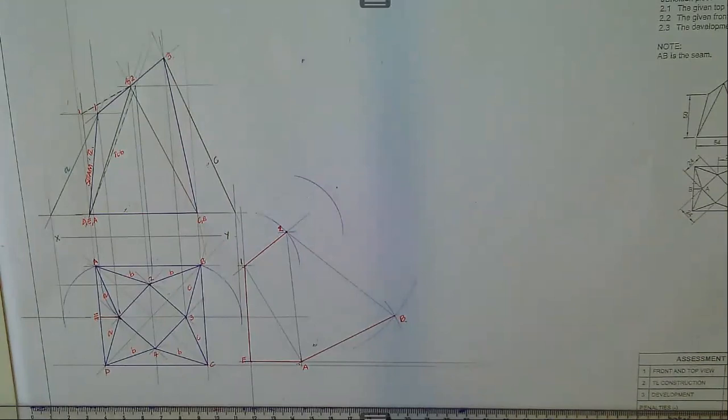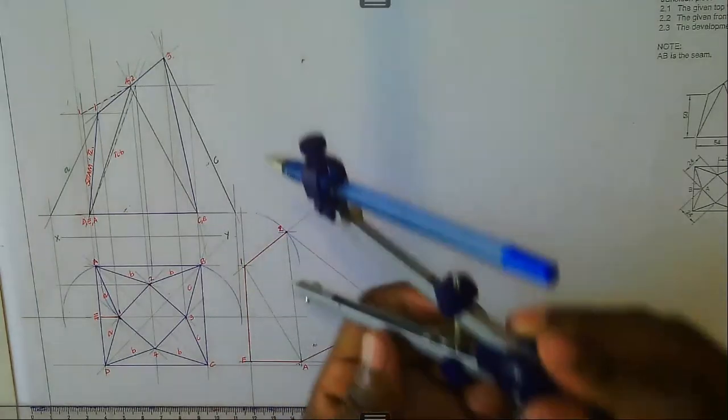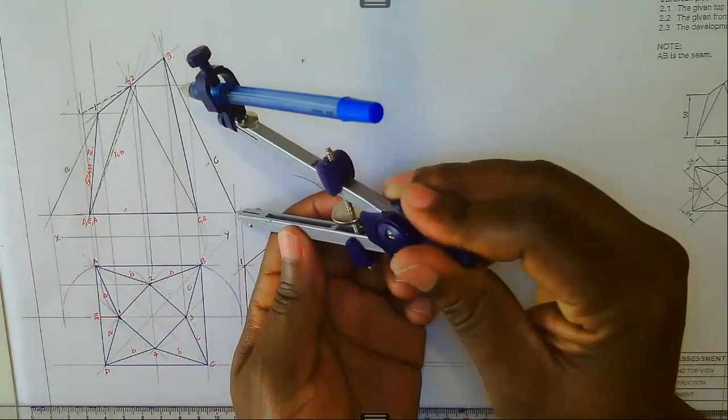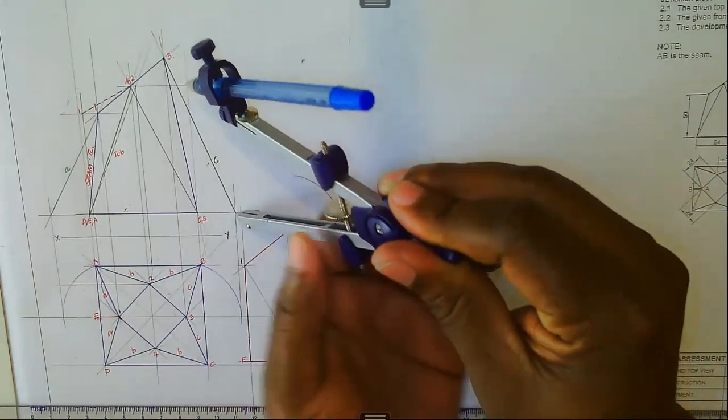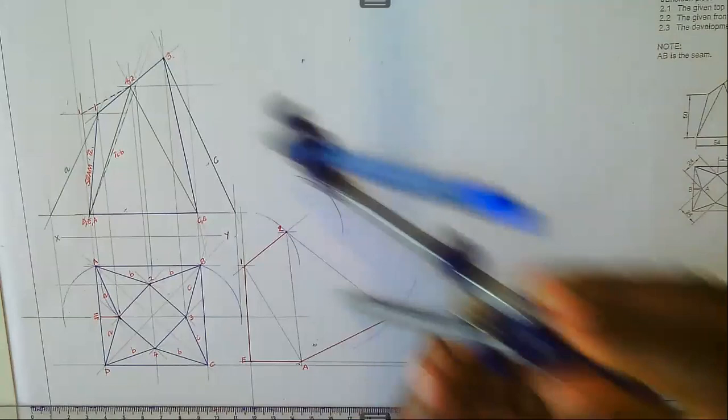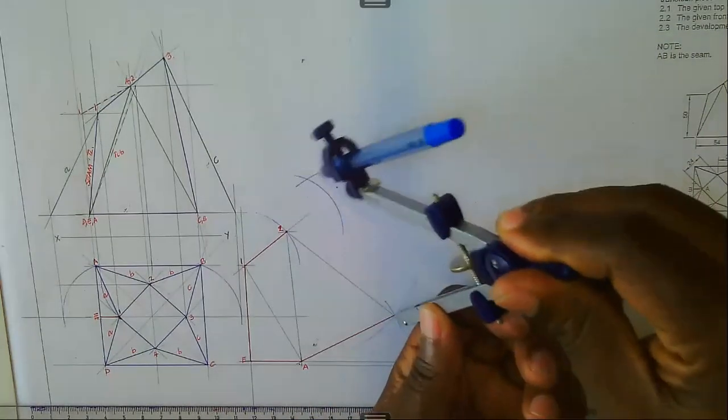It's a combination of 2 to 3 as well as B to 3. Make sure you have got 2 confirmed standing positions. Point 2 is there, point B is there. So for you to reach point number 3, you need to stand at point 2 to 3, point B to 3. Line 3C is represented by C. So we are going to take the true length from here, like that. Stand at B, then describe an arc. That's our point number 3.